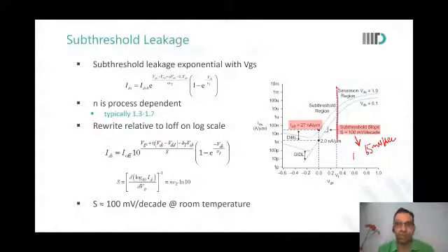So depletion, definitely. What is the difference between a depletion region and a regular substrate? Depletion means you have voided the excess carriers from that region, basically. So in a depletion region, all the excess carriers have been depleted. Yes, sir. So if you inject some electrons from one side, because there are no other carriers and there's an electric field across the depletion region, these electrons will move very quickly across it.